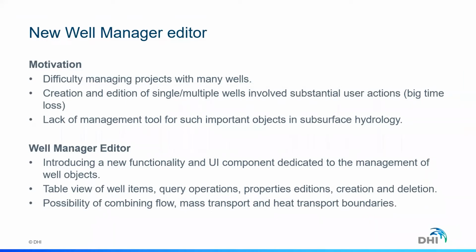So we introduced a new component called Well Manager Editor. This component is a central location, a new UI component dedicated completely to the management of well objects. It's a very simple table, but it's very smart and user-friendly. You can do a lot of operations. You can change properties, create wells, delete wells, and a major advantage is you combine a number of flow boundary conditions and mass transport boundary conditions.